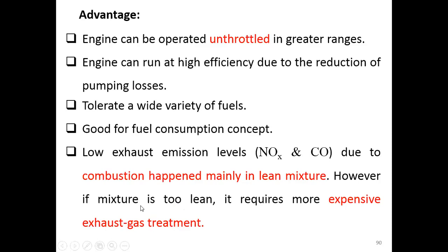Even though we have the combustion happen in the lean mixture, that means more air than fuel, then we have low exhaust emission level. But you cannot go higher and higher in the lean mixtures. There are caps or limitations on that. Because if the mixture is too lean, then you need to provide exhaust gas treatment.